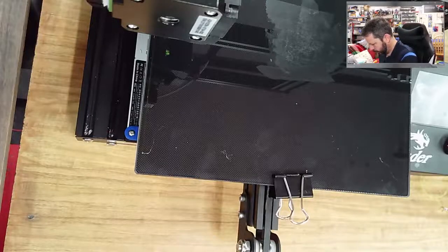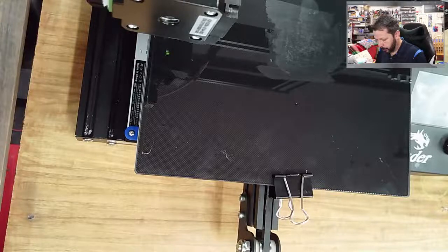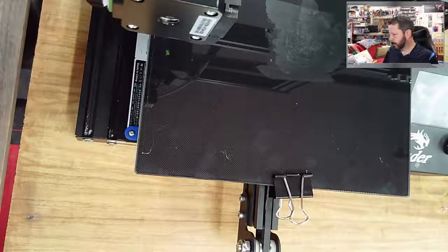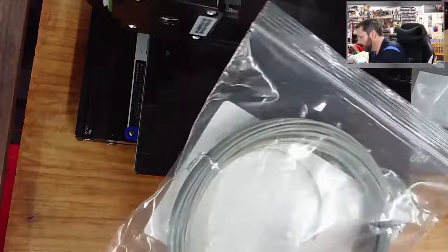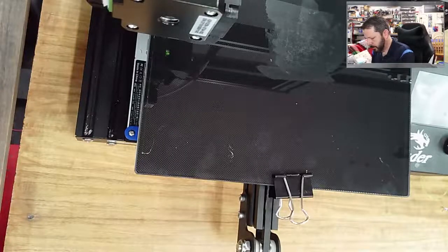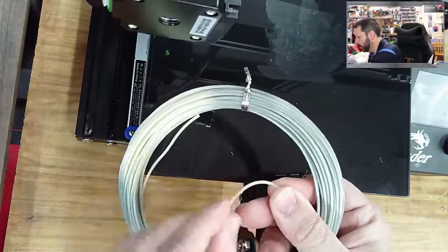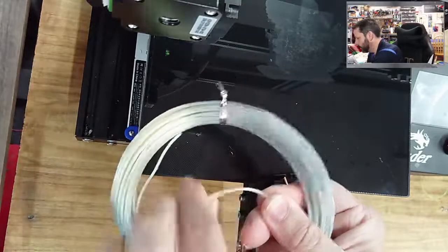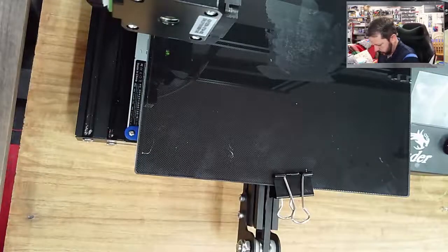It prints like PLA. I'll print some of it, just regular stuff like cubes or whatever. Again, these are older ones. PLA is not so bad at being not printable after being stored in a bag like this, so I'm not too worried about it. If you want to test PLA to see if it's going to be a problem, just take the end and bend it a little bit, and if it snaps, then it's probably got too much moisture in it. This one's pretty flexible, so I think it's going to print fine. Actually, just holding it there, you can kind of see it changing color.